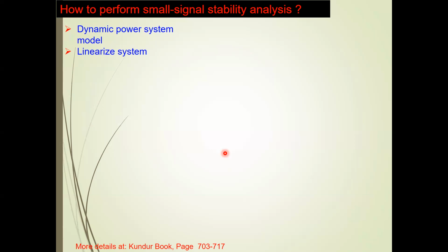That I agree with you, because if you want to model your transformer for short circuit, for fault analysis, then you have to take into account the saturation effect, and then you have to decide the relay setting, relay operation, and the circuit breaker. At that point I agree. There you have to take this saturation effect also. That will be a non-linear model of a transformer. But if you talk in terms of rotor angle or frequency stability, with respect to the generator, the transformer is a stationary device, stationary equipment. Am I right?